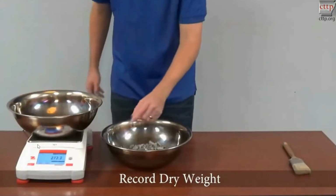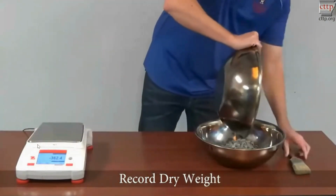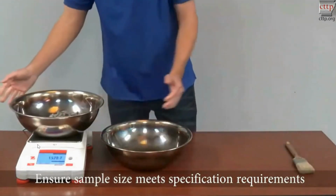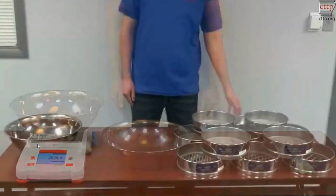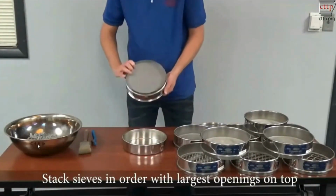Here is the dry sieve analysis. Ensure that the sample size meets specification requirements. Stack the sieves in order with those having the largest openings on top.